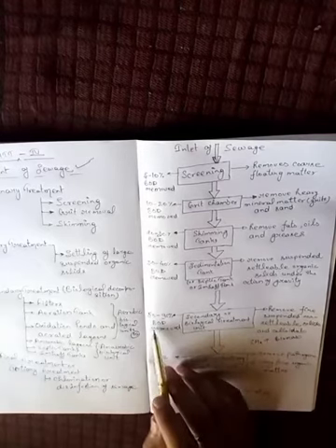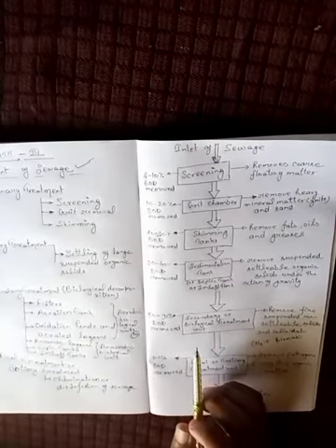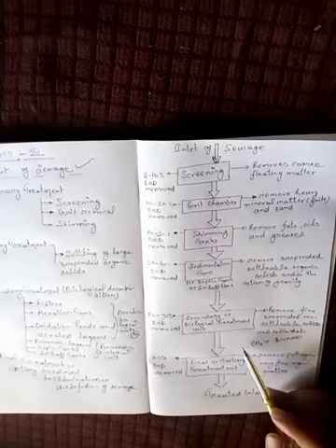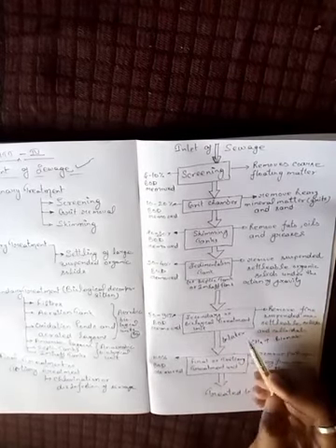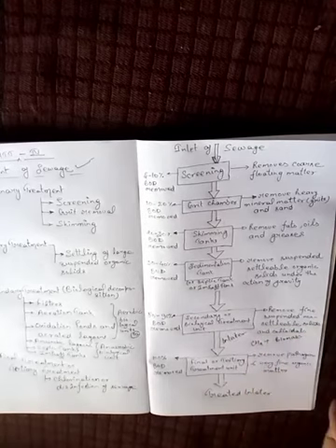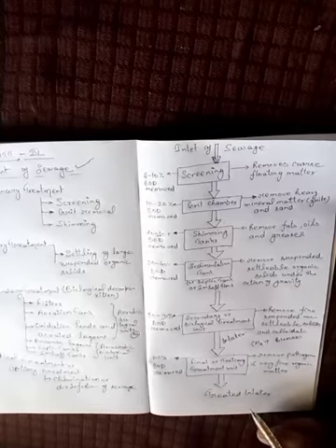In this step, 50 to 95% of the BOD can be removed. You can directly use the water for various purposes after this step, but for drinking purposes you have to disinfect and chemically treat this water.